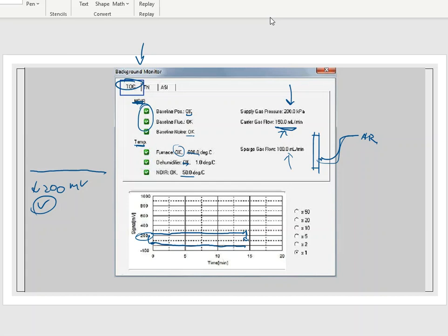The last thing that they want is to hire someone to come in and run TOC samples, have a problem with the machine, not want to fix it, and then continue to run samples on the machine just because they know how to bypass those features. So good luck getting data, and good luck getting the correct data if that's what you decide to do. So these settings and these protocols are in there to stop you when there's a major problem. So the flow rates are constantly measured, the temperatures are constantly measured, and the detector is constantly double checked to make sure that it's all working the proper way.